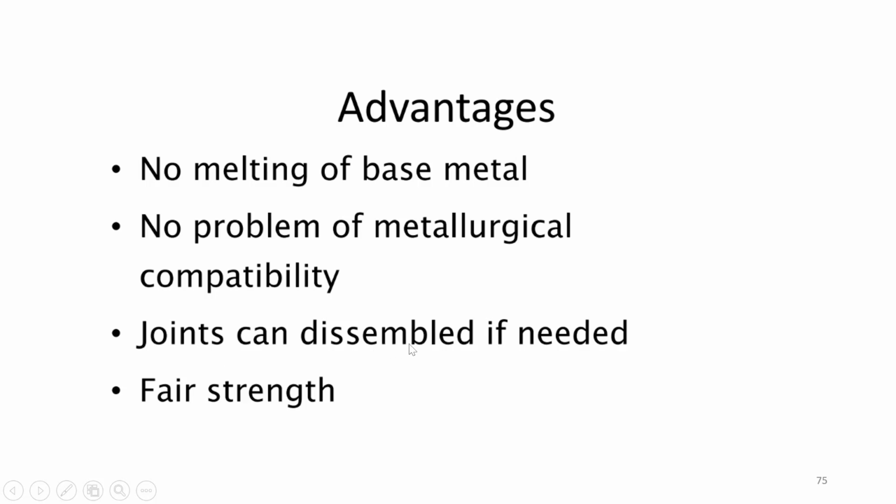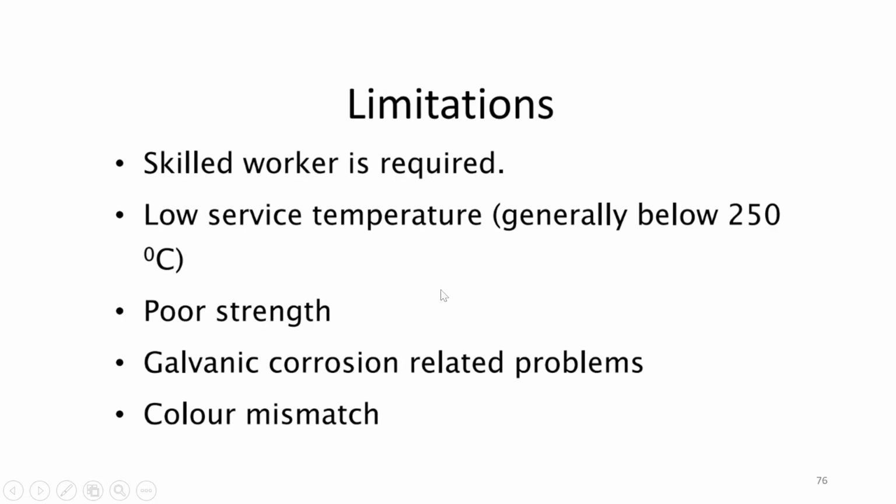Joints can be disassembled if needed and it has fair strength. Limitations: for brazing you require a skilled worker and low service temperature, generally below 250. If you go above this, then the strength of the joint will reduce. Okay, there is poor strength and galvanic corrosion related problems.